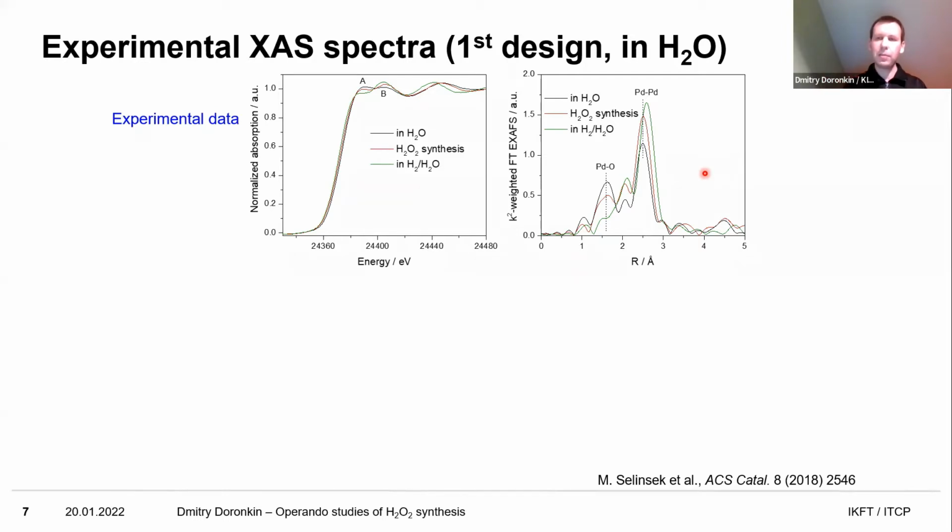And at the outlet, it may happen that there are no reactants at all left, and the catalyst sees only products. So it's quite often the case that if you try to measure somewhere in the middle, or at the inlet, or at the outlet, you will see different spectra. And simply because of the kinetics, you have different environment, depending on where you measure them. So you need to measure ideally at 2 points, always. And also purely for statistical purposes.